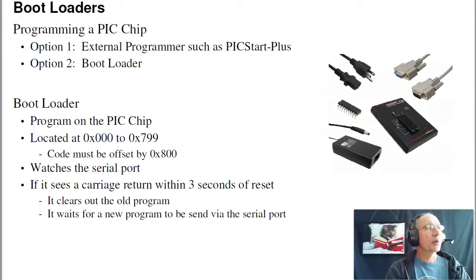Now to start with, there's a couple ways to download programs to a PIC processor. That's one of the most important parts about any microcontroller, how to get your program on it. There's quite a few different options for Microchip. There's a PICkit Plus. That's kind of what I use when the kits come from DigiKey each summer, and I assemble the lab kits. I take the chips from DigiKey, which are blank, put them in a PIC programmer, and program in the bootloader. You can program anything onto a chip with something like a PICkit Plus, and there's many other ways to do that.